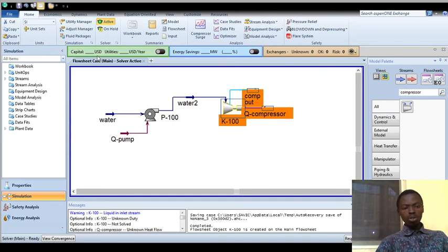So you should now go back to your design, go to your parameters, and see what you have here. You have your adiabatic efficiency as 75 again. Now if you remember, for your pump also, you have the adiabatic efficiency initially at 75. Your system can only operate at 75 efficiency. That's like the maximum it can operate at. Do you get that? So let's go to our ratings, go to your worksheet and then look at it.